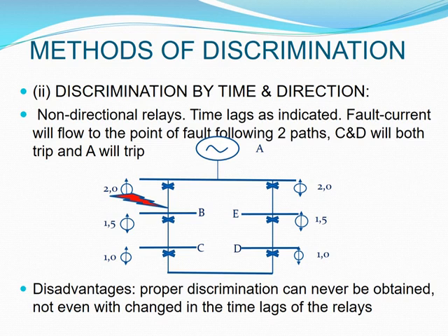And if the fault is introduced where this lightning strike is, which is between your A and your B bus bar, the fault current will have two paths in which it flows. The first one will be going down from that fault, towards bus bar B and all the way around. And your other one will be going through your bus bar A. So those are the two fault current paths in this network.